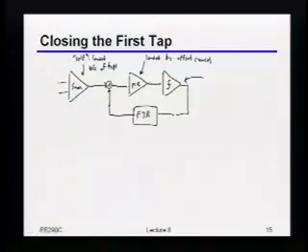Because if I do, then that implies that my transmitter has to be sending huge swings, and I'm just going to be spending lots and lots of power. Okay? So if I look at that comparator, there's going to be some minimum amount of time it takes me to just resolve the small input signal. Right? And that minimum amount of time is going to be something like, whatever my input swing is, let's say divided by 2. That's, of course, after the DFE.